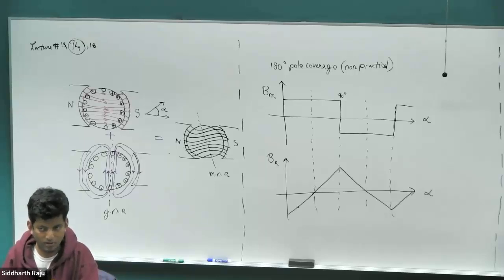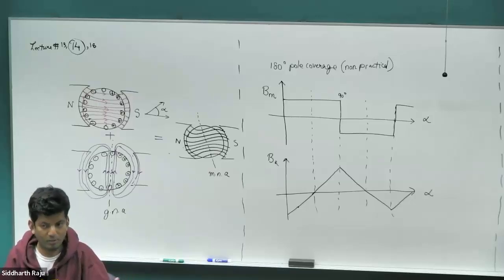AC motors, whatever controls we create and so on and so forth is to make sure that it operates like the characteristic curve of a DC motor. So it's important that we understand how they work, what the problems are. Right? We've already seen one of the problems with DC motor, which is basically the brushes, which are quite lossy. Today we're going to look at the other problem, armature reaction, which makes them somewhat not too compatible for when we go to very high power applications.